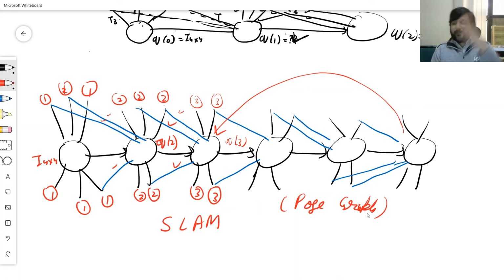We take the robot on a tour. So that's exactly what we did when you people joined the institution. We took you on a tour. So somebody guided you, you kept on looking at different buildings, somebody kept on telling you, this is CC1, this is the computer lab, this is the robotics lab, this is the library. And that's exactly what we do with the robot. We take the robot on the tour, and the robot keeps on looking here and there. It knows it started from the charger, so it keeps on calculating its position every time, and it keeps on looking at what are the different places of interest.